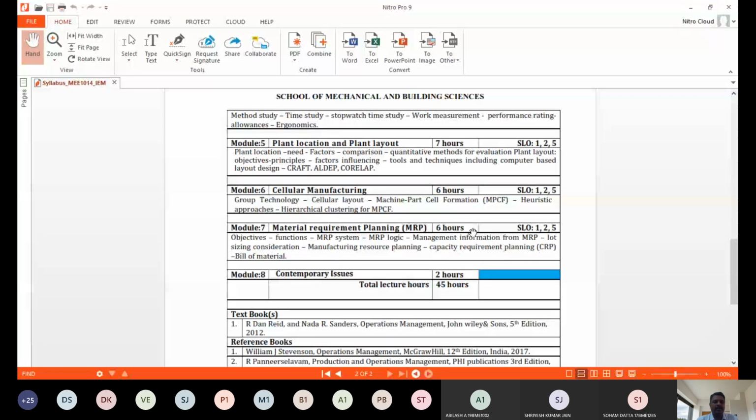From the design document, an important document is the bill of material. If you want to fabricate or assemble a final product, what are all the products that you need to buy? You make an order, buy it well before, get it QC, quality check inspected, keep only the required quantity in the store, take it from the store, assemble it, and then